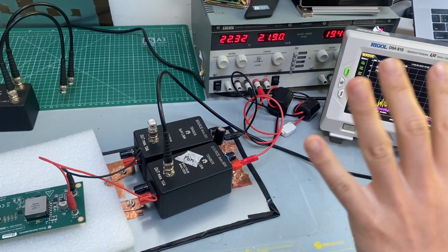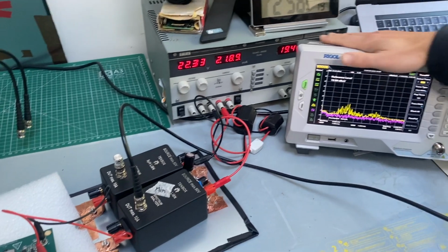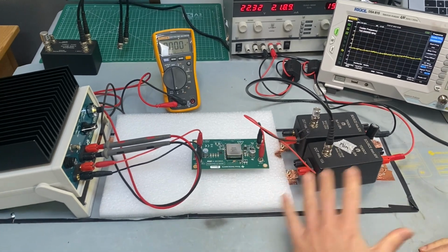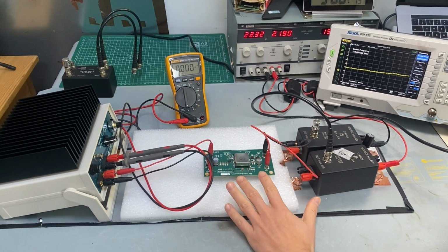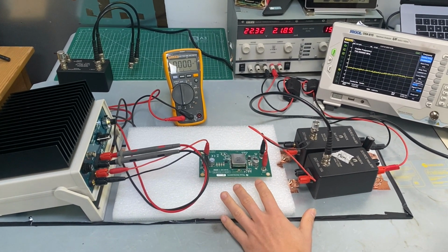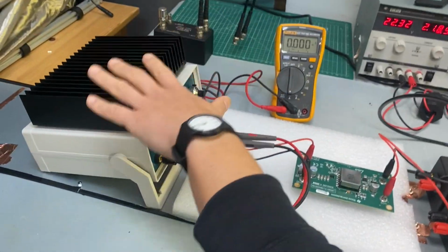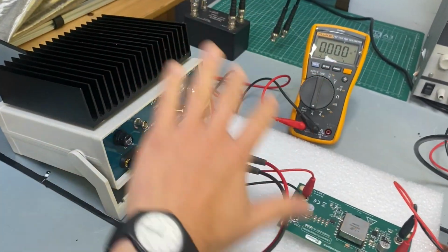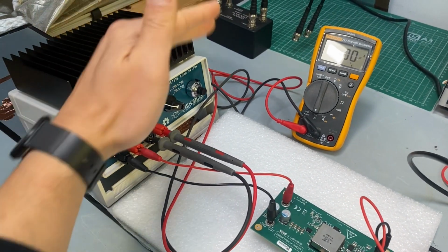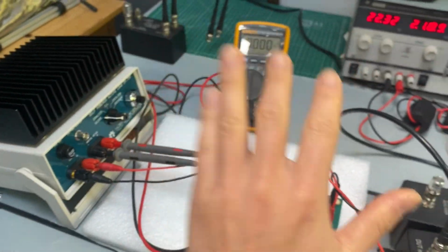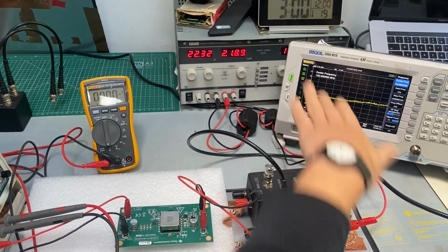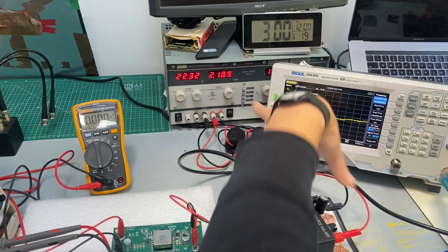setup, and I'm going to use this setup to demonstrate how I normally use my spectral analyzer. Okay, we set up our demonstration here. This is a flyback isolated power supply evaluation board from Texas Instruments. This is our active load. This load is used so that there's no noise actually coming from this load, because it's a self-powered active load. It doesn't have any switching inside. And we power the unit up using 2 LISNs. And as we explained, between the LISN and the power supply unit, we have some filtering here.